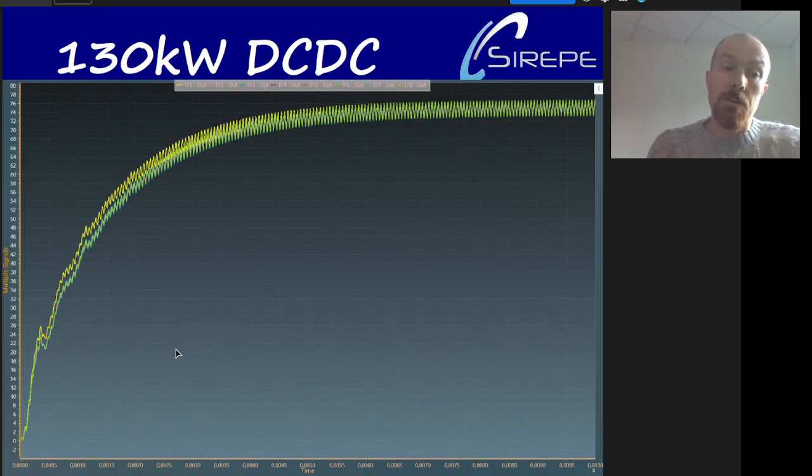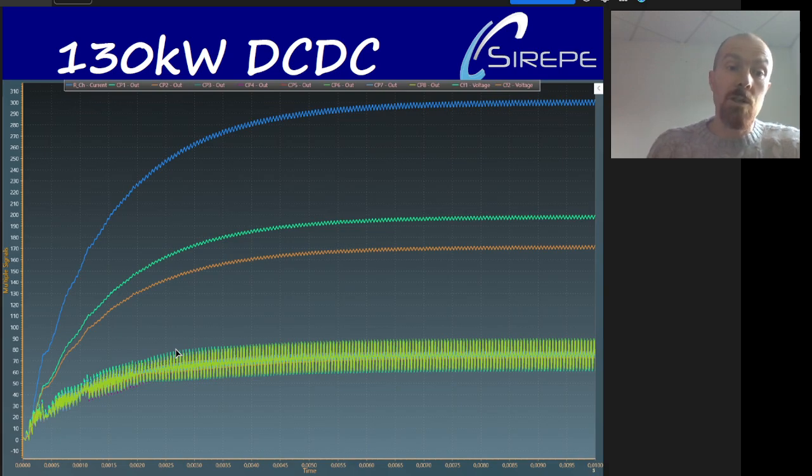Okay, but this slight difference leads to a big difference in positive voltage relative to negative voltage at the output of the converter, and leads to high frequency ripple at the switching frequency in the battery current.